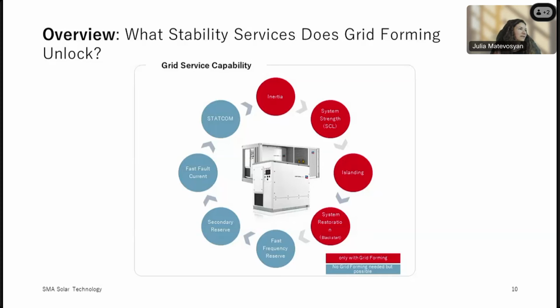I think the question was asking, well, it says controlled inertia, so I wouldn't call it that from grid forming because it's not controlled or activated, right? Inertia is kind of an inherent response from a grid forming inverter, but it's asking what's the difference between physical inertia and grid forming inertia, if you will. I understood it to be comparing a synchronous machine against inverter provided inertia.